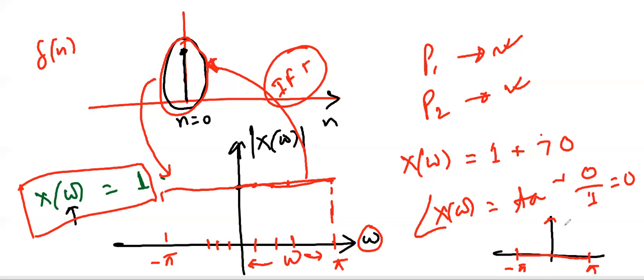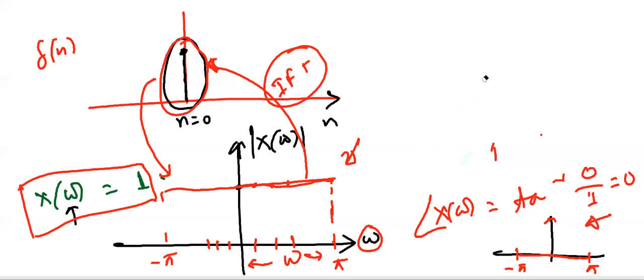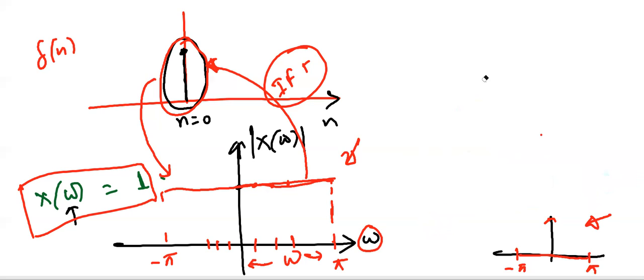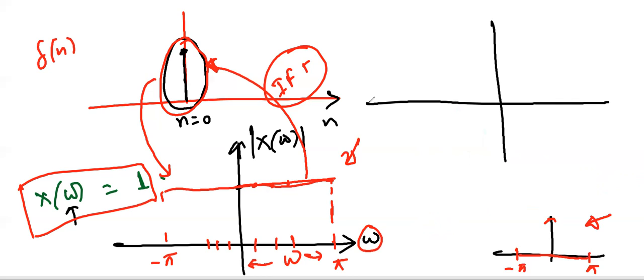And as I already mentioned, you need two pieces of information: one is the magnitude response, another is the phase response. From these two, what we can observe is very interesting. What frequency components do you need to build the delta function? As one of our friends already mentioned, you need all the frequency components. This is the way we can observe it.